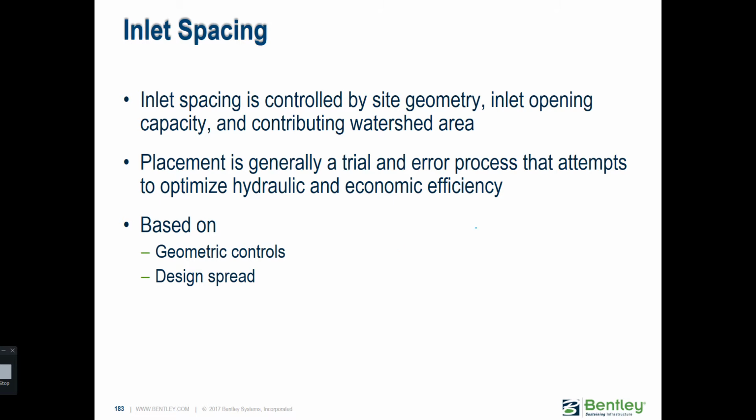And also it's kind of common sense, because if this is the profile of my road and I have something like this, you know that at the lowest points you're going to have to place an inlet, because it's just logic. The water will collect easier there. So again, trial and error.